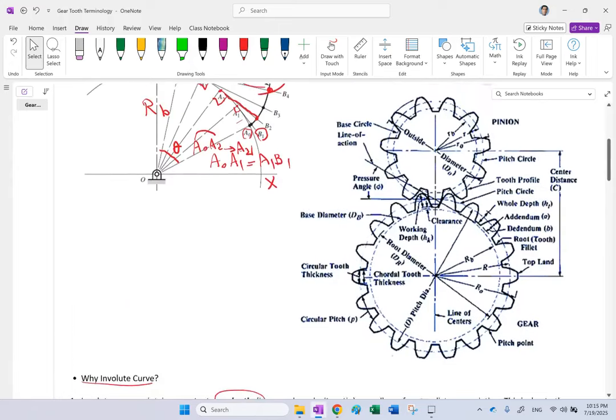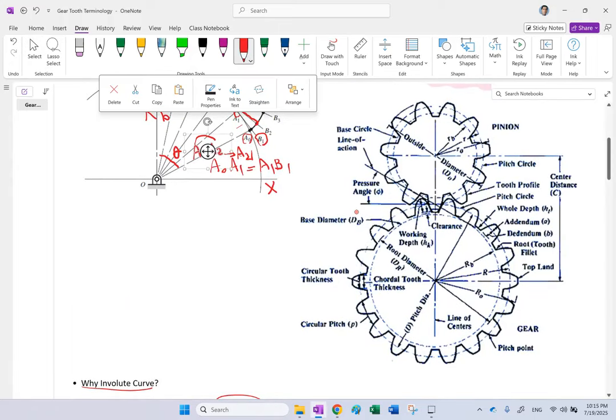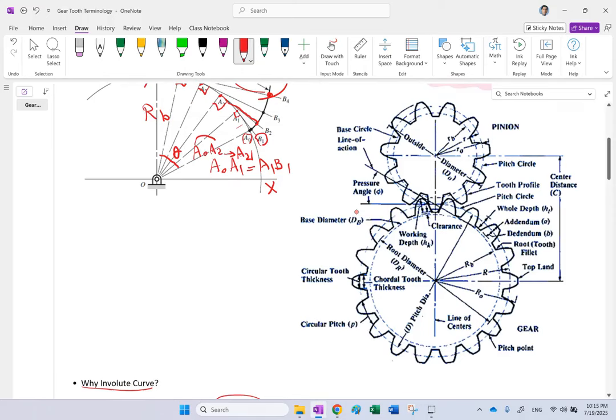First of all, if you have two gears that are working together, we say the gears are meshed or engaged together. They are working together, right? So typically you call the bigger gear the gear, and the smaller gear you call the pinion. So if you have two gears like this, engaged and spinning together, then the speed ratio is typically defined as if one of them is the input and the other one is the output. So let's say, for instance, in this case, this pinion is the input and this big gear is the output.